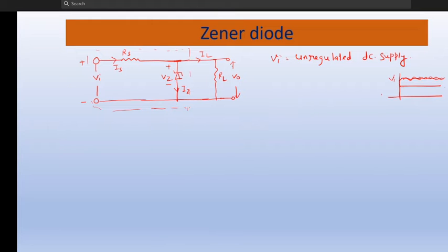So what we do is, after rectification, in the rectifier output where we get the DC, we put some filters to remove these ripples, but still there are some ripples that still exist. They cannot be filtered out. So we need some mechanism so that we can have a regulated output of the power supply, so that it should not vary, right?